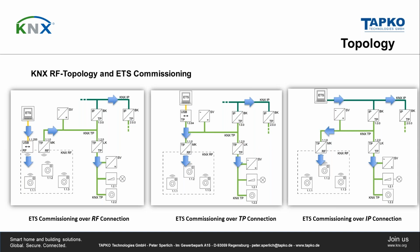On the right-hand side, you can program over IP, connected with an IP router to the TP line, and the TP line is connected to RF. And you can also see that you can have remote commissioning. You can sit in your office and connect to the project of your customer, and then you can program not only the TP, you can also program the RF.